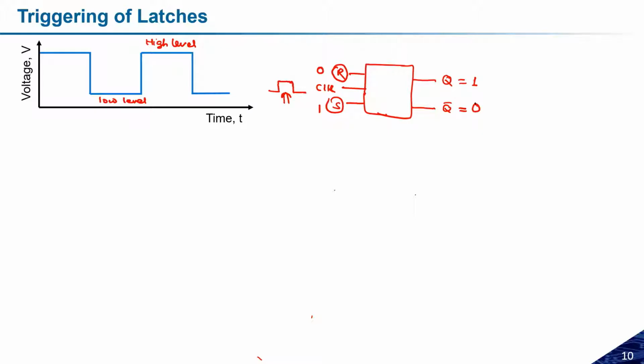But what I'm expecting is that in each clock there should be one change, so the data should not flip. Suppose I have a high clock pulse that activates this flip-flop. During this, without moving into the next high or low cycle of the clock pulse, if there is some change in the input, then in a single clock cycle the output can become 0 or 1.